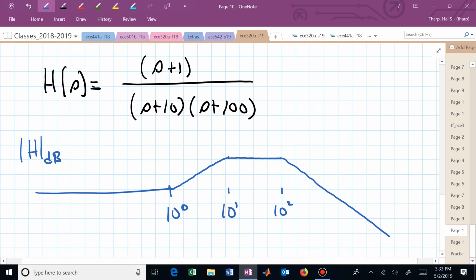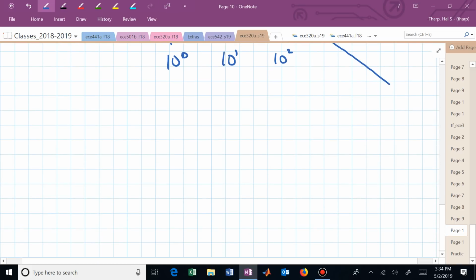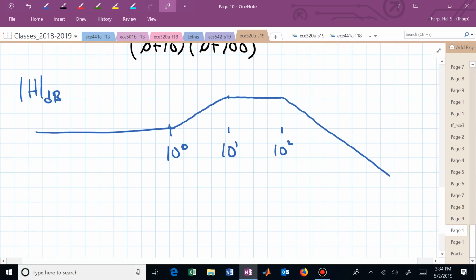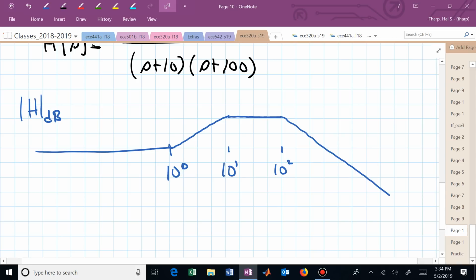And now what would you say this filtering characteristic is? So this one could go kind of either way. It's favoring a particular band, but it's also low pass in behavior. So I might have to give you credit for either of those responses. It's favoring a particular band, but a band pass usually does something like this, doesn't it? It's attenuating at low and attenuating at high. This one doesn't really do that. It's okay with the low.